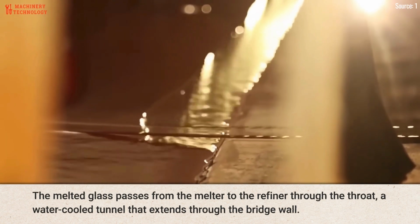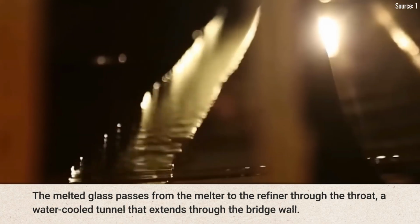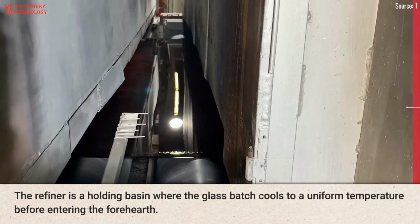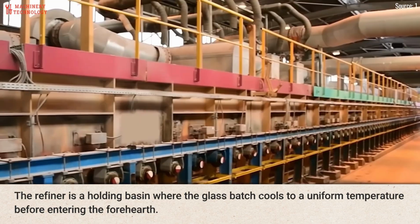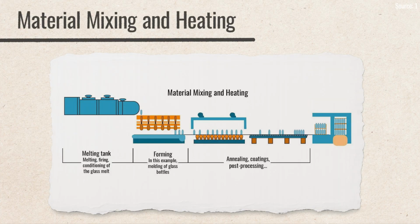The melted glass passes from the melter to the refiner through the throat, a water-cooled tunnel that extends through the bridge wall. The refiner is a holding basin where the glass batch cools to a uniform temperature before entering the forehearth. The process of material mixing and heating has been visualized in this graphic.